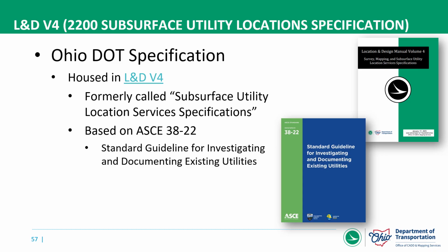Section 2200 talks about specifications, and there's a link to L&D Volume 4 if you want to take a look at it. Subsurface utility location services specifications is what's in there. It's based off of ASCE 38-22, the standard guidelines for investigating and documenting existing utilities.